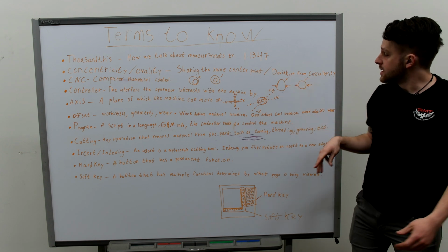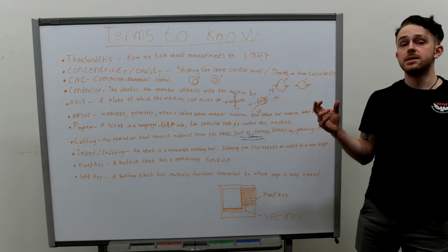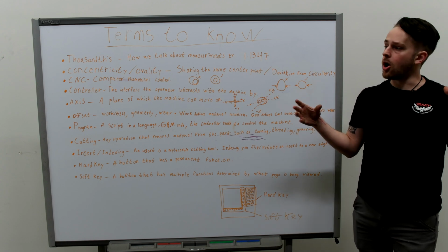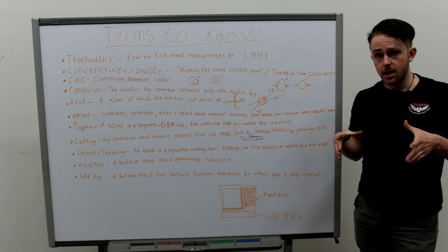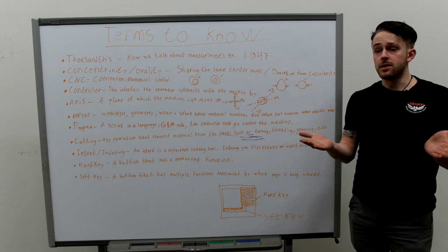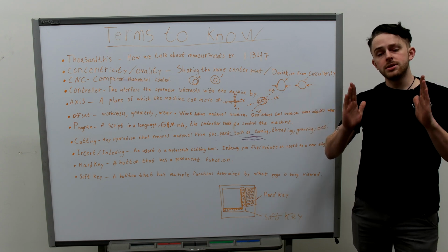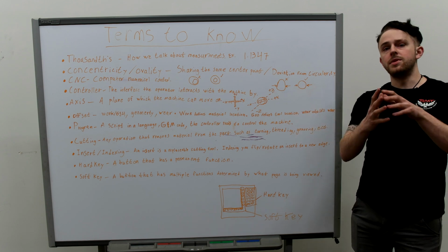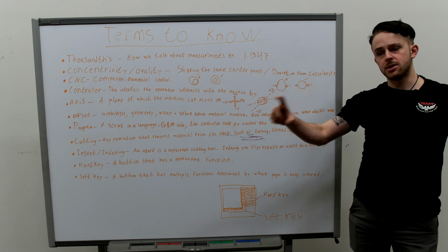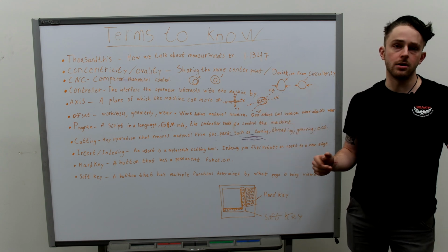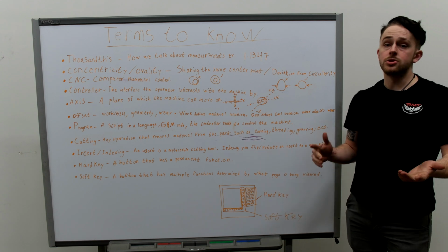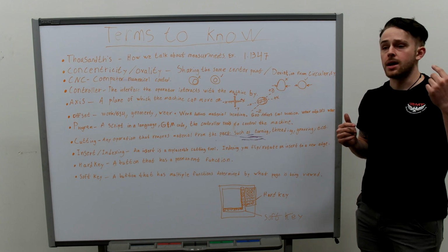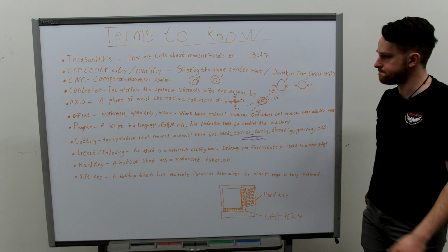Now, ovality is a deviation from cylindricity. This is important because if we are clamping onto our part in our TGB, there's a potential that the clamp pressure could be high enough that it squishes that material into an oval. And so obviously, then when it becomes unrestrained, the material will spring back and it will no longer fit or match our print. So just make sure that when you're setting up and doing things, you're looking for ovality as well as keeping an eye on your clamping pressure.